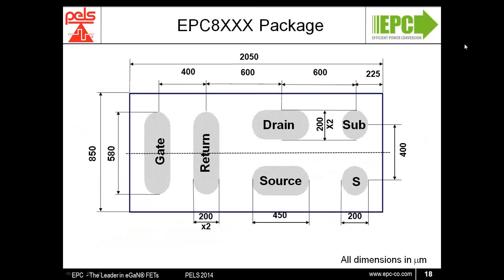To better understand how this works, let's consider two of these devices in series to form a buck converter or similar half-bridge switching topology. So here we have the top layer of the PCB with two devices shown facing up. If we remove the devices, we can see the gate terminations and the pinouts of the devices.